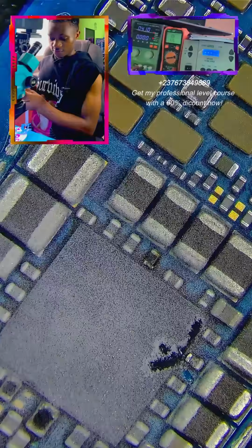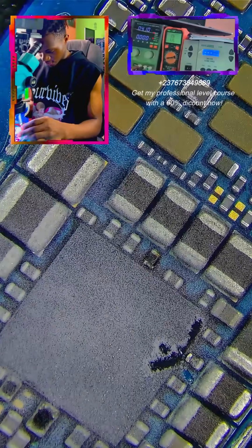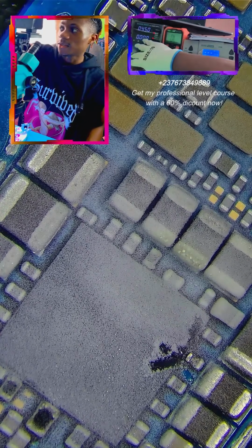So just for us to confirm that, let's focus on that capacitor again. And because it's taking, we can put this to 4.5. That's actually okay, and it's safe for this line. So let's inject the voltage again here. You can see the current consumption from the DC power supply, and if you focus on this capacitor here, you can see that it's heating up, right? So this is what I was saying.